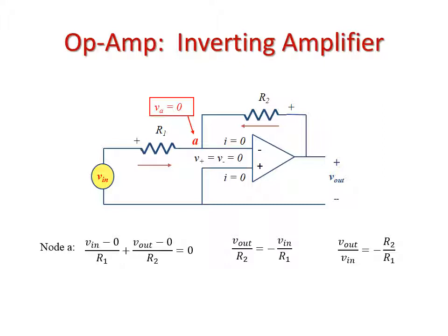So our nodal analysis allows us to create the amplification factor, the gain factor. If we want a really large gain, something extremely negative, we make our R2 value larger than our R1. Our R2 can be 1,000 ohms, and our R1 can be 10 ohms. Then we'd have a very significant negative gain factor. So that's how we calculate our gain, and that's how we calculate our V out, because our V out is going to be whatever the gain is times our V in.